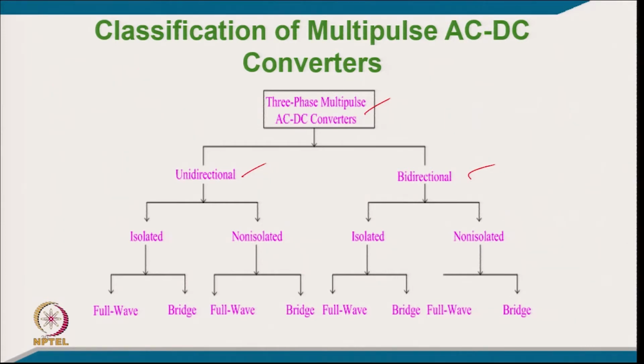So, in many applications which are unidirectional power flow, like process industry, your electroplating plant, electromining plant, people are replacing the diode thyristor with the diode and then using a single IGBT, even up to 3 kiloampere or 5 kiloampere order, they are available now. It does not require DC control, and a high frequency of the order of 3 kilohertz is reasonably well. So, there are plenty of changes.